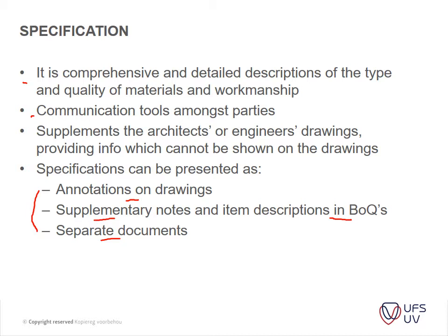Something which is not mentioned, but what you can use in practice, is photos as well. I've used that quite a lot, especially with refurbishment work, where you can't really describe how, for instance, if you need to fix cracks, it's nice to have a set of photos that can be linked to an item in the BOQ, because then the contractor knows exactly which crack you're talking about. So that might help.